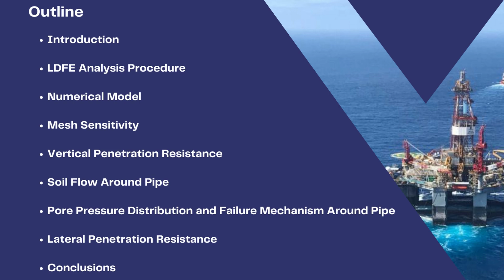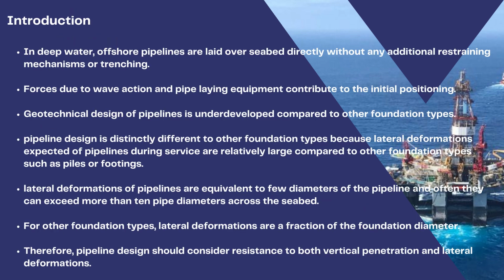First, I will give you an introduction about offshore pipelines. Then, the large deformation finite element analysis developed for this analysis, numerical model, mesh sensitivity, vertical penetration resistance of pipelines, then the soil flow and pore pressure distribution around pipelines, including the failure mechanism, lateral penetration resistance, and finally the conclusions. So, in deep water, offshore pipelines are laid over seabed directly without any additional restraining mechanisms or trenching.